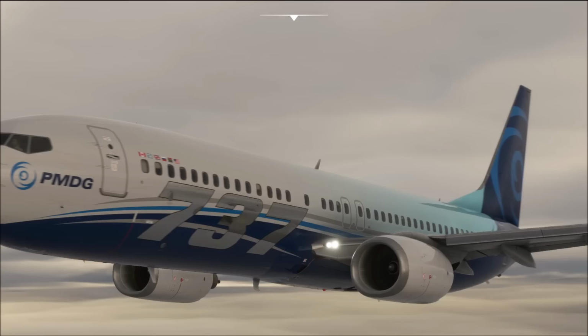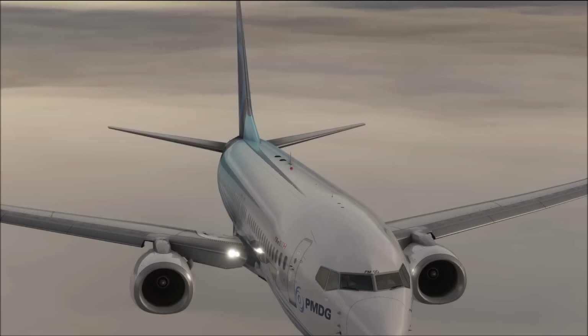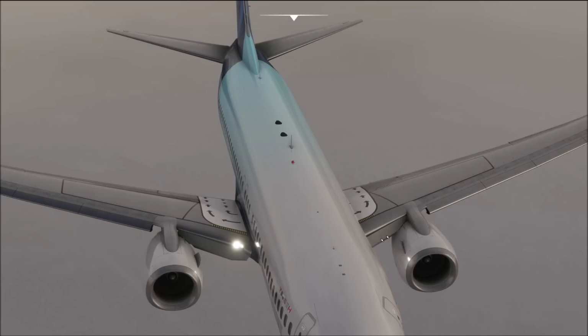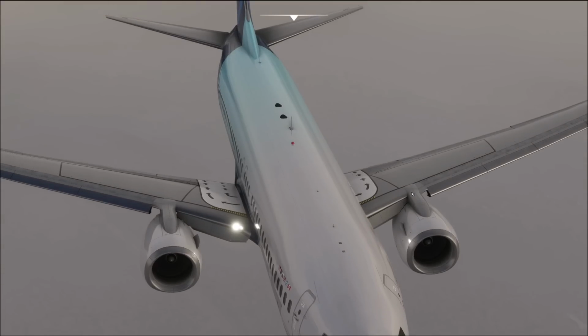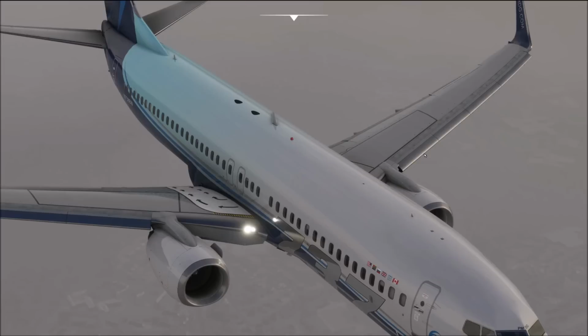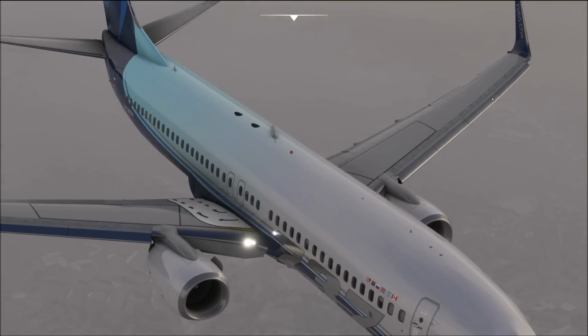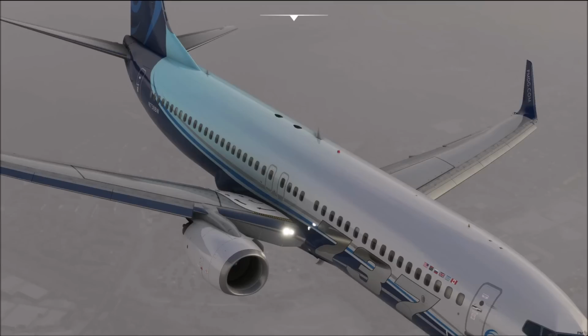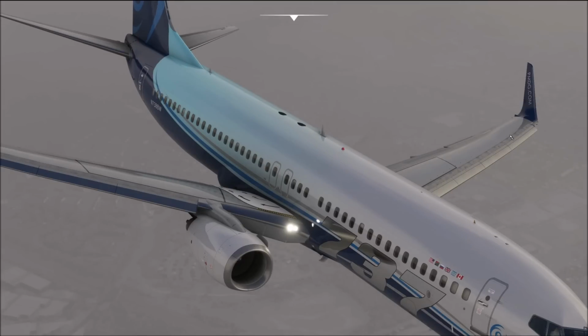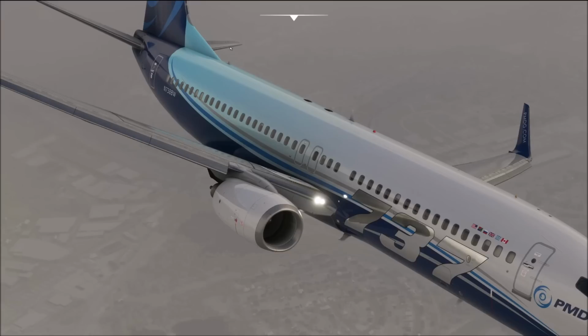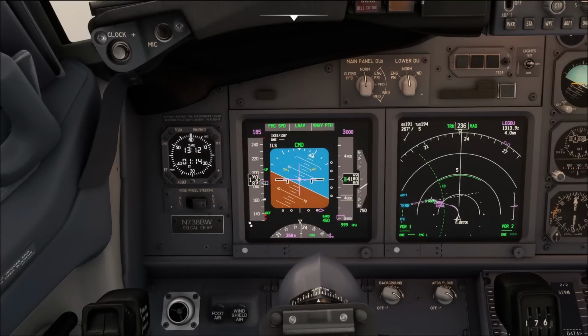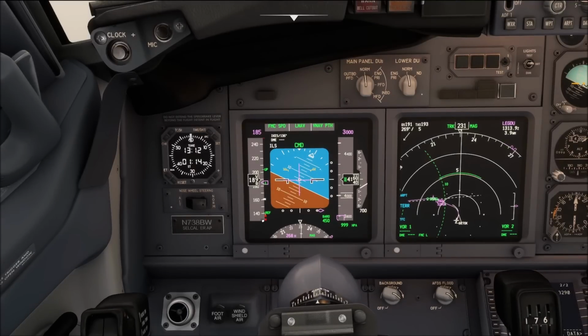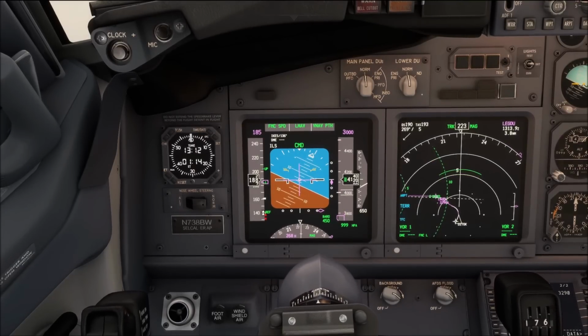looking at the wing up here, we can see the wing is divided in different parts. We have the leading edge flaps, which are not de-iced. Then we have our numbers 2, 3 and 4 leading edge flaps, which are de-iced, and the outboard one again is not de-iced. The entire tailplane is not de-iced either. Therefore, once we have actually used our wing anti-ice, the minimum maneuver speed on the PFD is going to stay increased above the normal values.